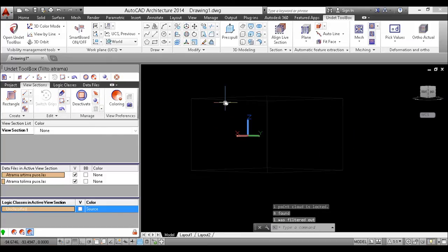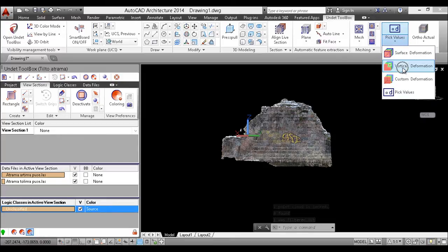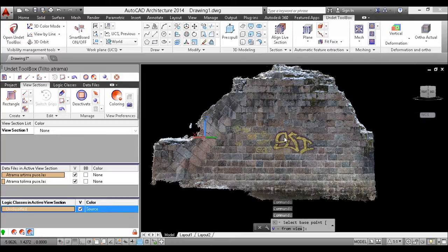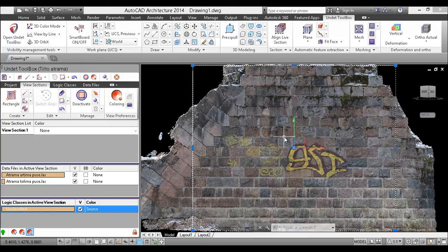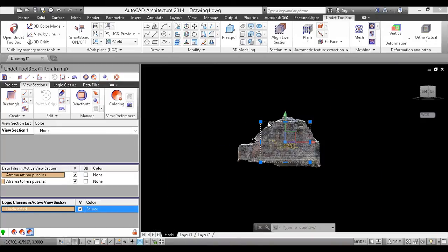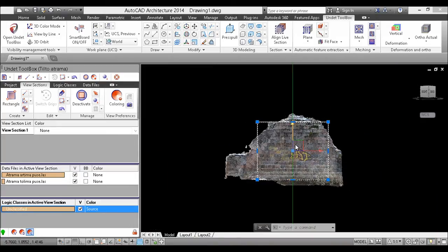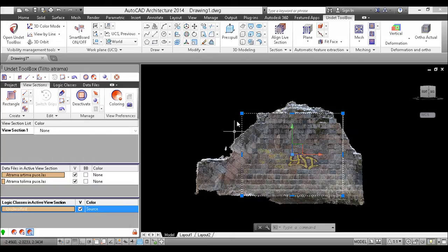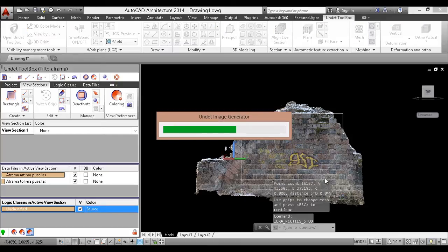Okay, let's delete it and let's now create another deformation analysis, which is vertical deformation. I'm gonna click somewhere on the surface, and you'll have your polygon with regions appeared. Once again, it stopped over here and over here because it calculated a plane only within this region, because in this and this region there's already another planes or other structures like edges and so on. So let's press enter right now,